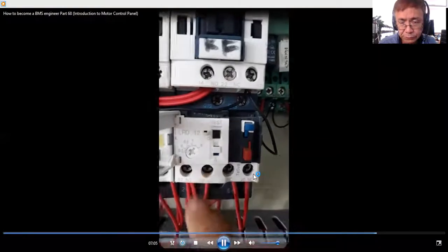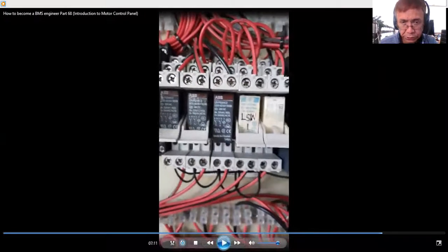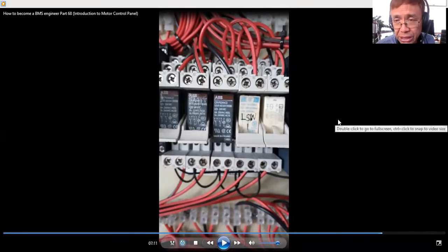I have also here some small relays, miniature relays. Actually, I'm using these relays for the automatic operation, the automatic control wiring diagram for this twin exhaust fan. Because as you know, when you are doing the BMS, the different BMS points for this twin exhaust fan should be provided from the motor control to your DDC IO module.